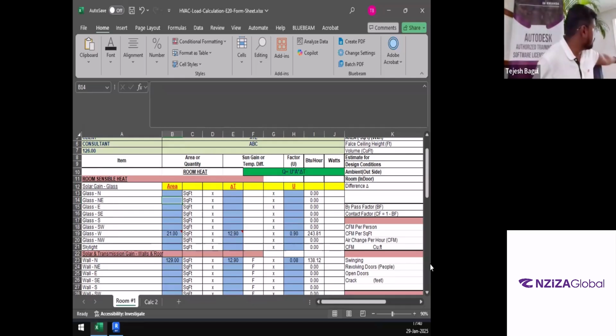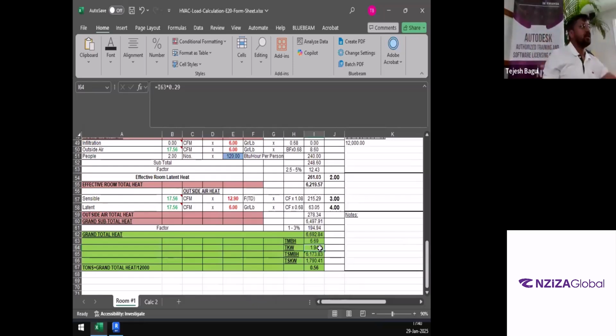Okay. So now, is it clear? Unit or 1.9 for this particular patient room. So the equipment that now you're ordering from the vendor, be it Daikin, Mitsubishi, Carrier, whoever it is, it needs to be rated for minimum 1.94 kilowatt. Minimum. You can go above it, that is fine, because not every manufacturer will have 1.94. They might have 2 kilowatt, 2.5 kilowatt, whatever it might, right? Similarly, it is 1 ton, 1.5 ton, 2 ton, 3 ton, 4 ton, 5 ton, right? It is good to go above. Do not go below that range.